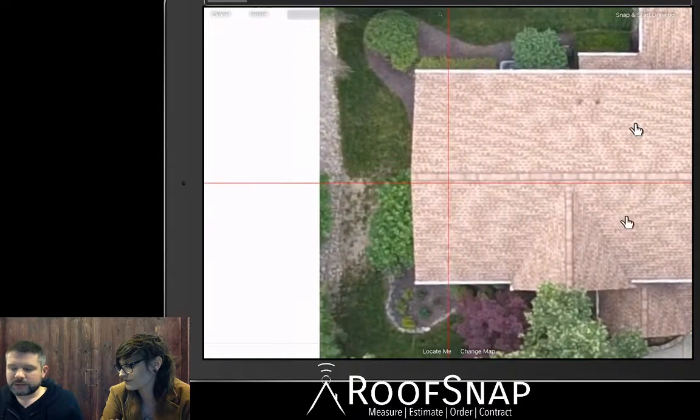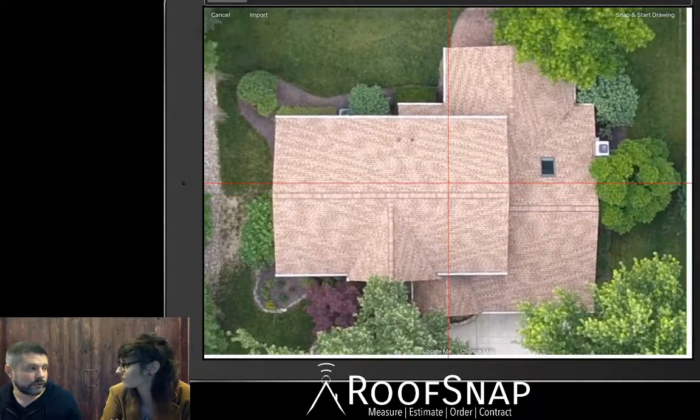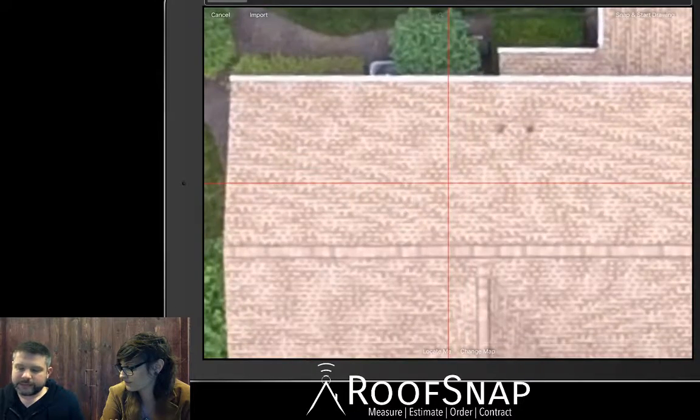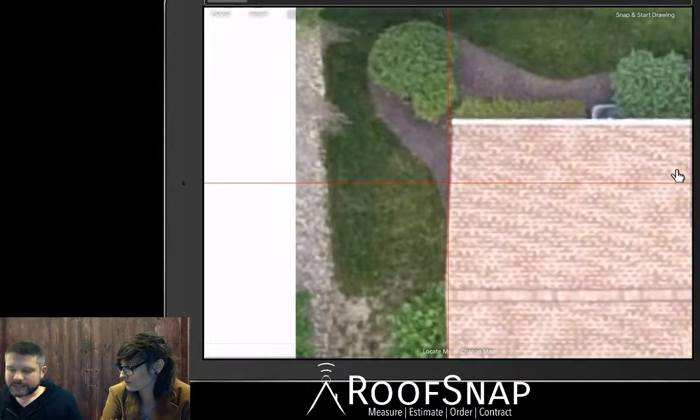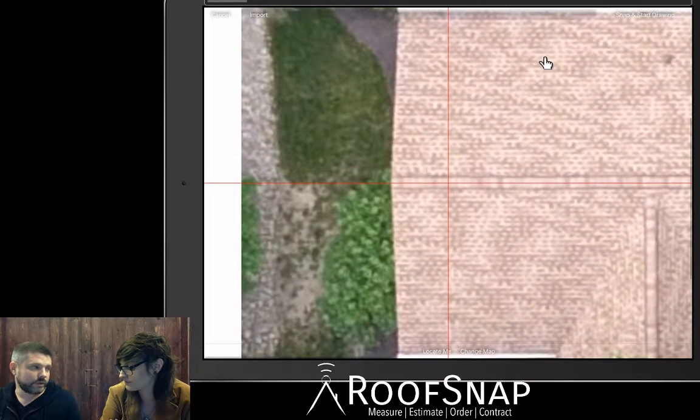I would typically just use the ridge line as the length of the roof and draw the rakes at 90 degrees using 90 mode straight off from the ridges. So it would actually end up drawing a line that would be a little bit outside the gutter length at the bottom, but I would follow the actual length of the ridge across the top.